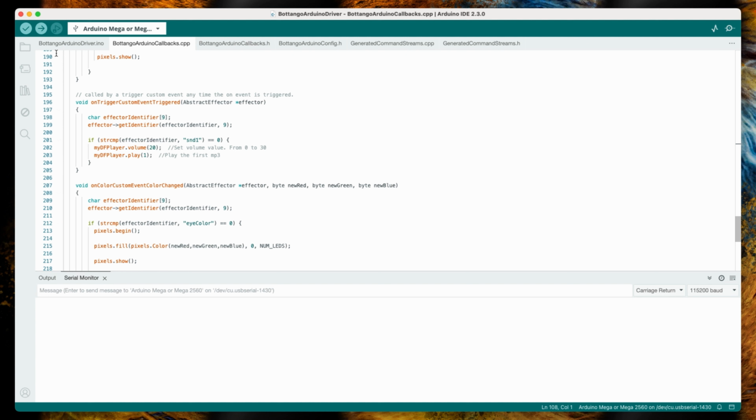So the first file that you would expect is 0001.mp3, the second one would be 0002.mp3, etc. If you copy those files in a different order on the SD card, the file that you copy first, that might be called number 7, would be called by this function if you ask it to play the first file, because it got copied first onto the SD card.